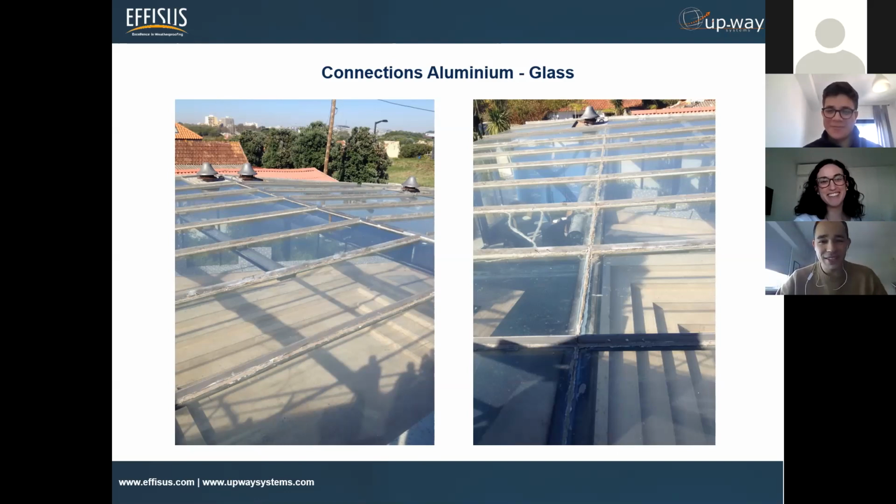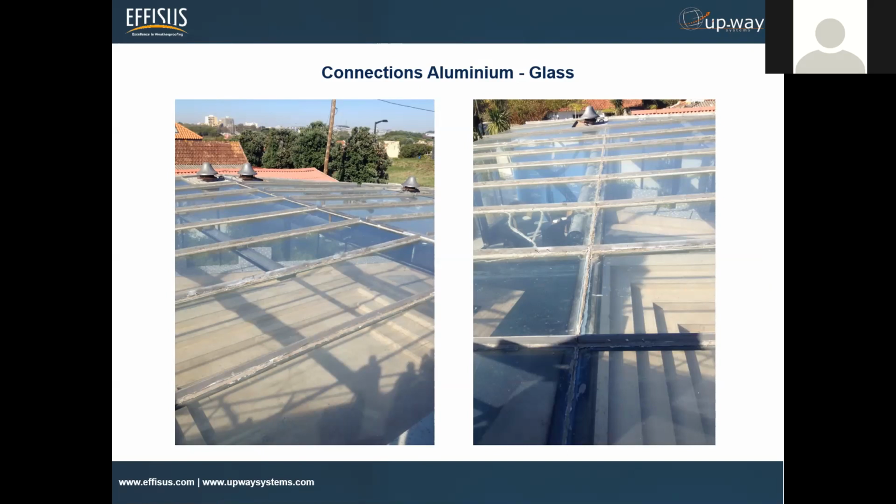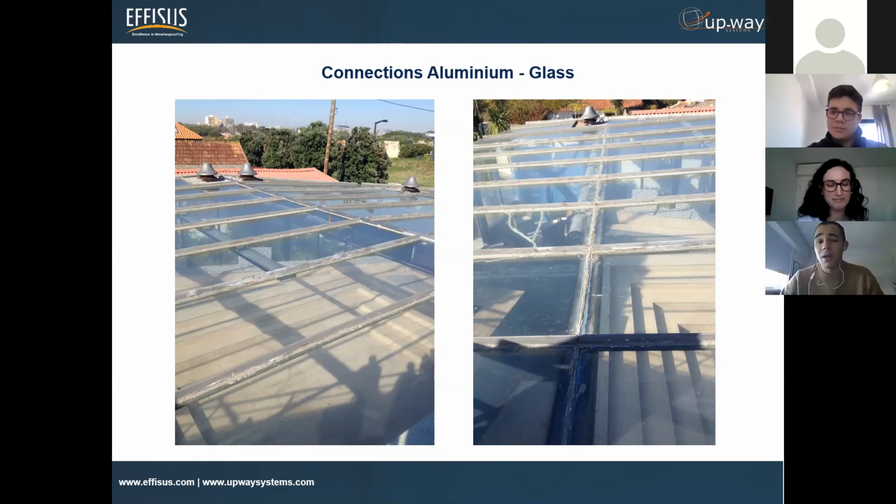So talking about these connections, aluminum and glass, it's like you said. When these materials start to expand, the traditional solution, the silicone-based solution, cannot keep up with the expansion and the movement, and starts to crack. And with glass, another important thing to say is that most silicone-based products don't adhere very well to glass. Most of them are not very compatible with glass.